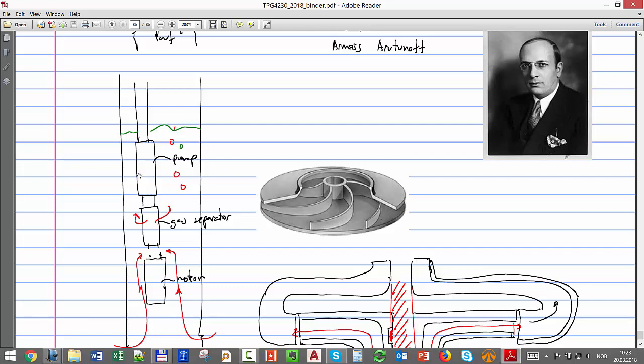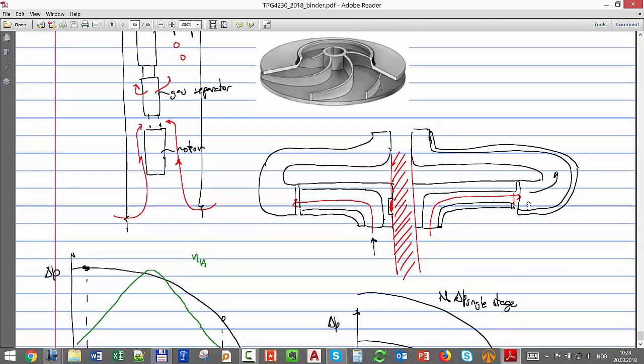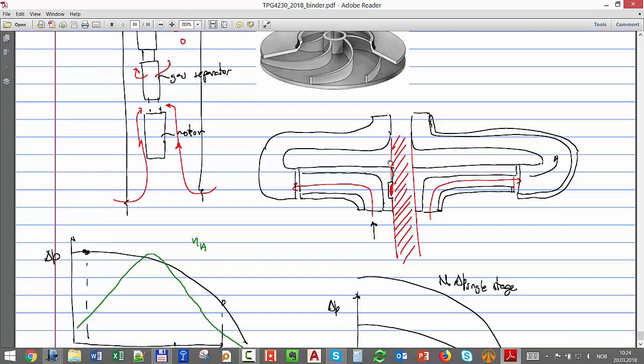And I told you there are three parts. You have the pump, which is basically, yeah, I left it. So basically, you have a lot of these things stacked one on top of the other, and they are rotating. The fluid enters into the ring and then is trying to go through these passages and then is discharged out. And then you have to send it to the other stage again, so you have to be redirected through a diffuser where you recover pressure until you go through the next stage. The part which is rotating is here. I should have used another color, but okay.